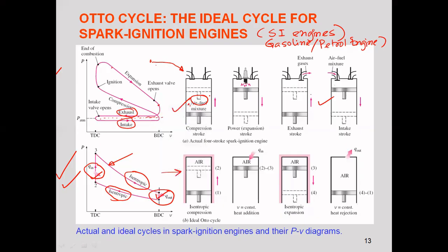The pressure inside is very high, and the pressure outside is atmospheric. So there is a pressure differential, and if the exhaust valve is open, immediately there will be a flow because of the high pressure differential. There will be a flow from inside to outside. And so what will happen? If the piston remains here, then immediately some exhaust gas will be rejected into the atmosphere.